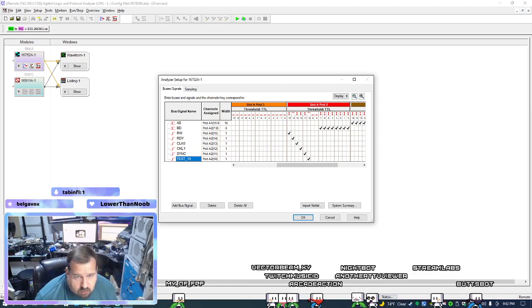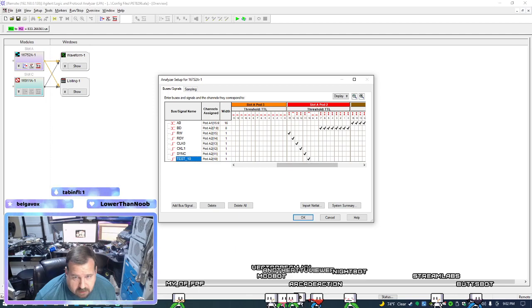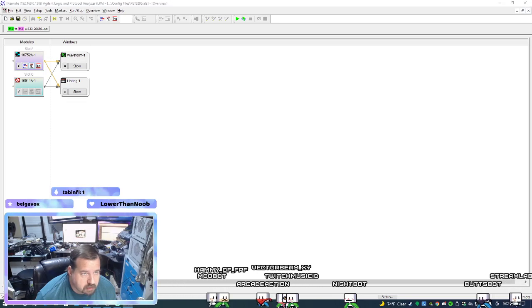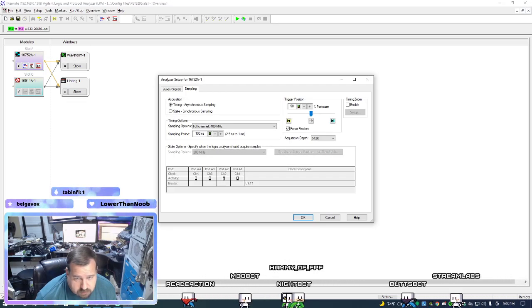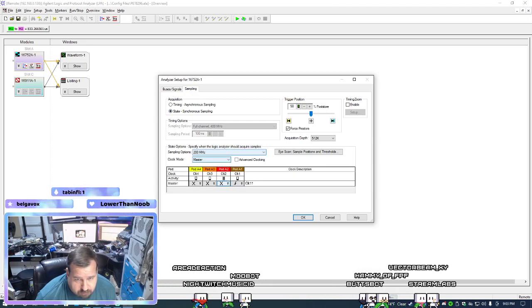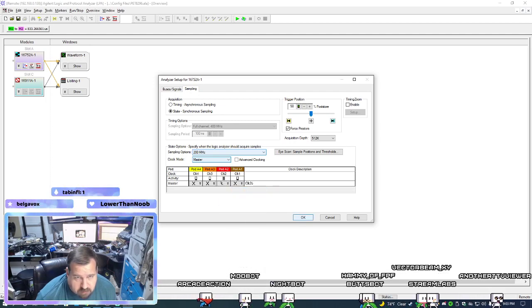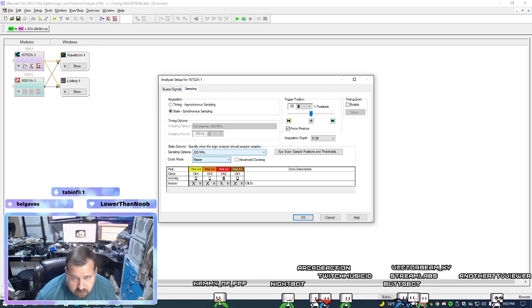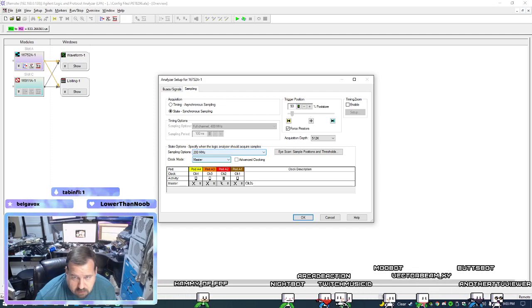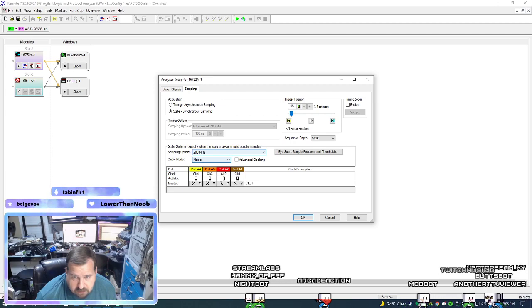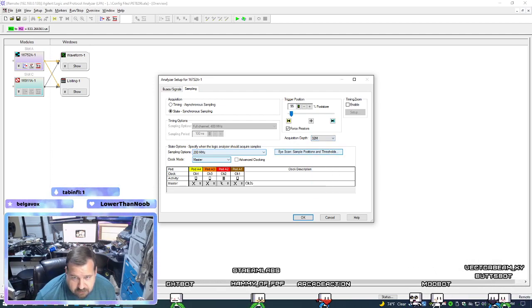So I added clock 1, or the clock input, to the board. So if I go into here, we're going to switch to state. Hope it doesn't blow away all my settings, and we're going to do it on the falling edge of that. This one we don't care about. Okay, saved all my bus signaling. Whew. Move the trigger position back to the beginning. And I can capture 32 megs of data.